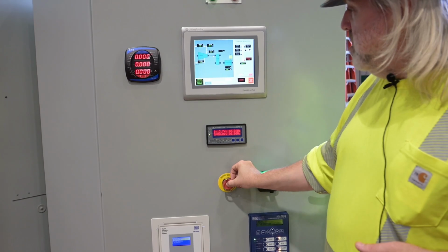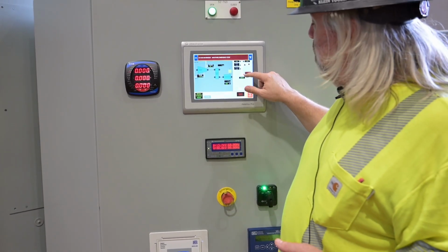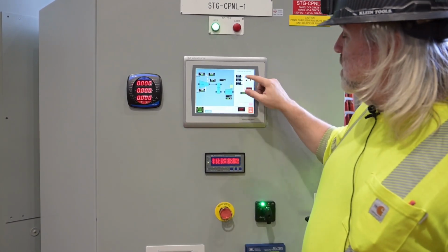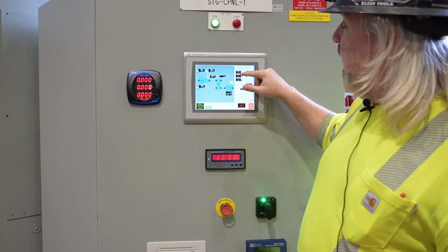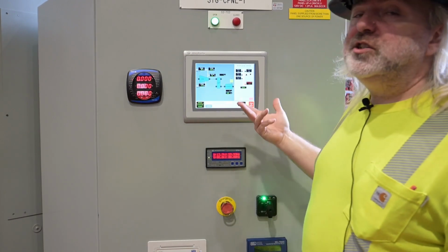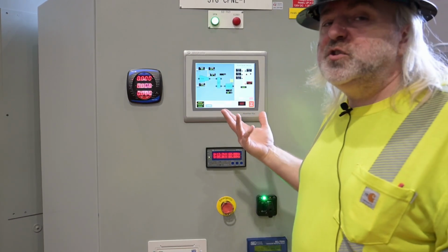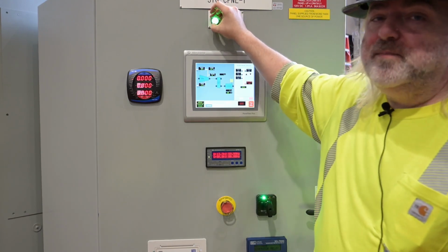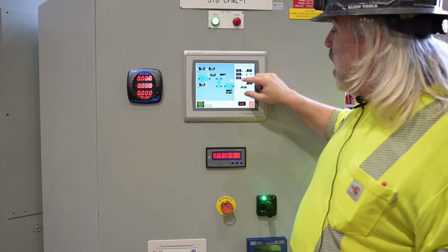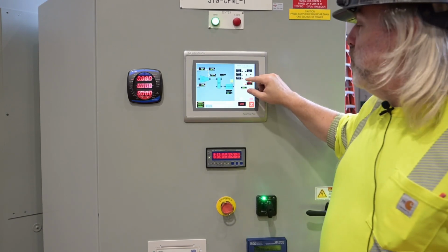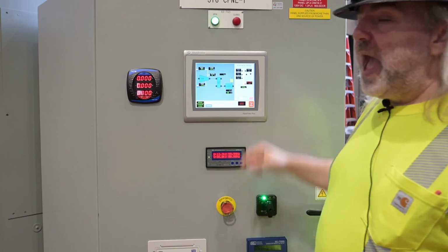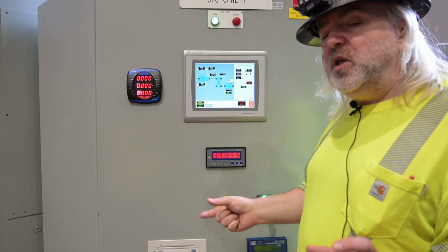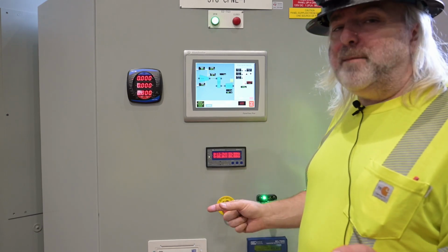So when we're shut down, tripped, we're putting 0% in. Once we reset and start, the speed indicator will go green and it'll start to change to try and achieve rated idle speed, whatever the speed set point is. Again, speed is in control when the breaker is open. When the breaker is closed, exhaust pressure and kW will be green and they will be in control of the valve. And again, they do that by looking at their set points versus their actual process values and manipulating their outputs to try and get to set point.